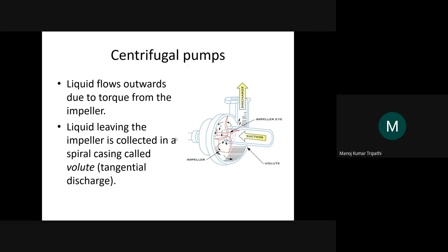Now this category of pumps, centrifugal pumps, these are the most common for household purposes for water. So you can see this is the suction perpendicular to the pump, and then this is discharge tangential to it. The water, I'll use the word water because generally it is used for water. It may be used for other kinds of fluids as well. So from the suction line, this fluid comes in, generally water. Then these are vanes. This is known as impeller. It rotates, it gives the fluid a centrifugal motion so that the fluid gets thrown outwards, and then this design is known as volute. It is like a spiral casing where the fluid goes outwards away from the vanes and then discharges from this outlet.